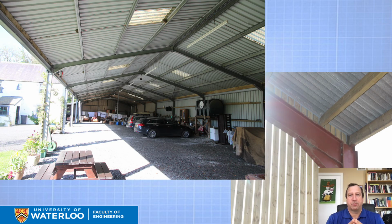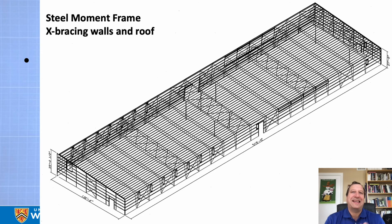For lower rise buildings, we sometimes see this in small sheds and pavilions because, again, the simplicity of the construction overcomes the additional cost of the materials. And this happens to be just a farm shed in Scotland with very simple galvanized connections that can be bolted together and very quickly produce a shed. Where we see a lot of moment frames is in pre-engineered steel buildings that I'll show you.